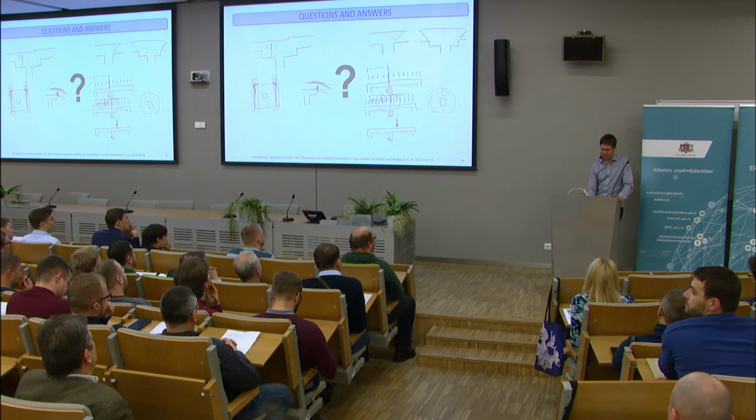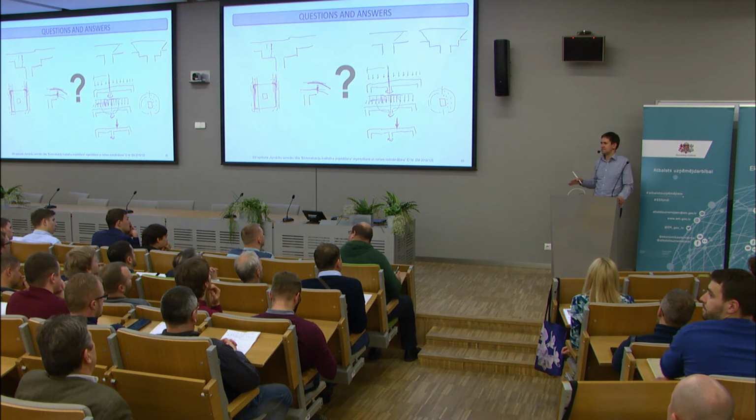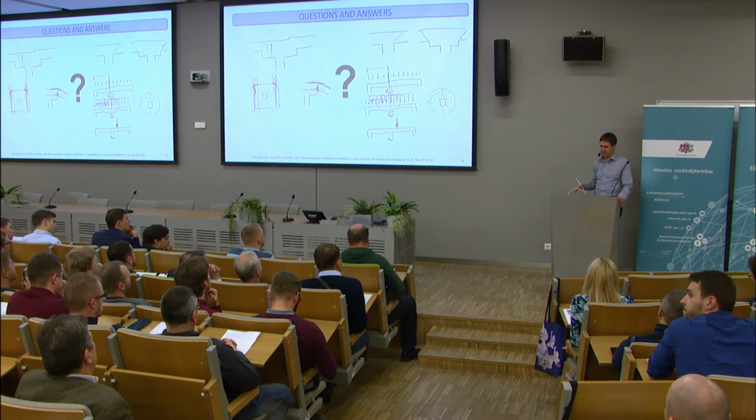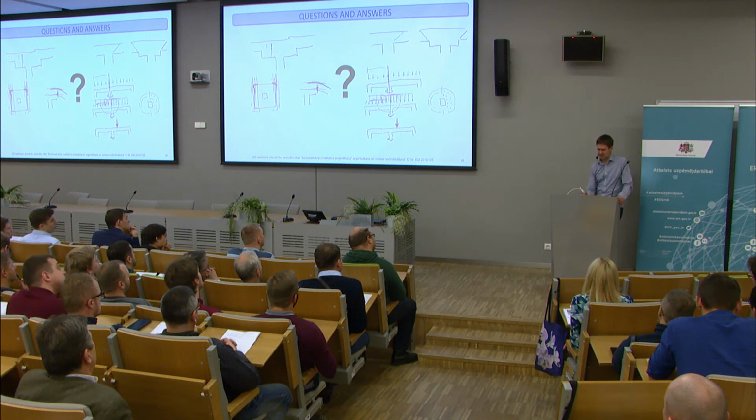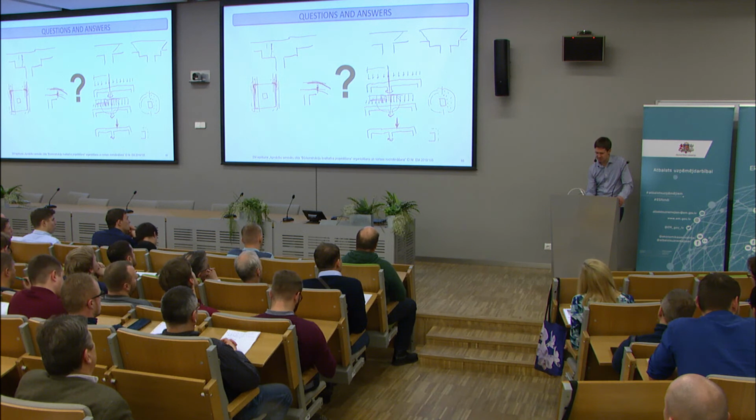And for the case when you have concentrated shear forces close to the column, then I think the best method we have is to calculate the shear flow and look at the distribution of shear force. So when you have load in here, you will have higher shear force in here.